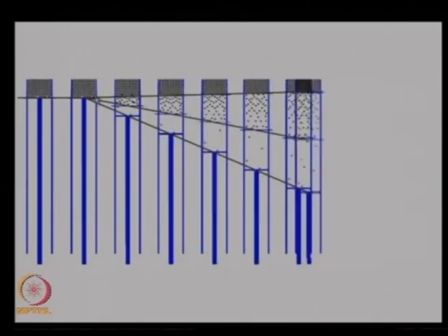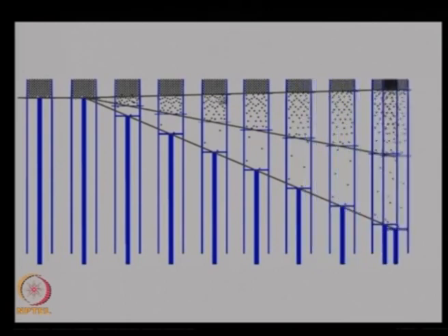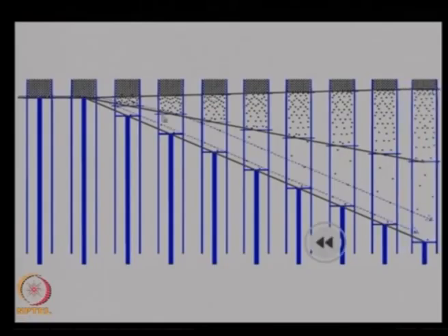And this is your first expansion wave going that way, the time trace of the first expansion wave, and this is the time trace of the last expansion wave that is going here. And then this is the time trace of the piston, which is equivalent to our wall in this case. So I am going to have an expansion fan. This is a region where there are so many expansion waves, and the expansion waves are more and more apart as time goes. So this whole region is expanding out like a fan.